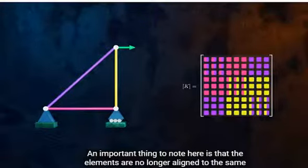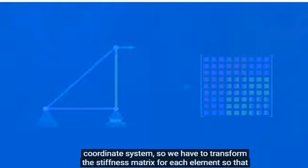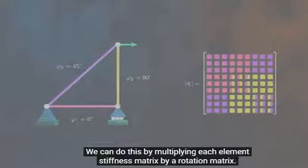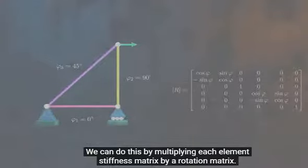An important thing to note here is that the elements are no longer aligned to the same coordinate system, so we have to transform the stiffness matrix for each element so that it aligns with a global coordinate system. We can do this by multiplying each element's stiffness matrix by a rotation matrix.